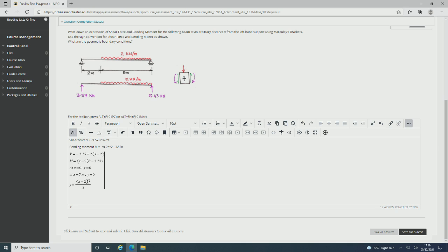So which one do you think would have the higher second moment of area about this plane? So that type of question could be there. You don't need to calculate, but you need to choose one. Of course in this case, the highest second moment of area would be for the I section.